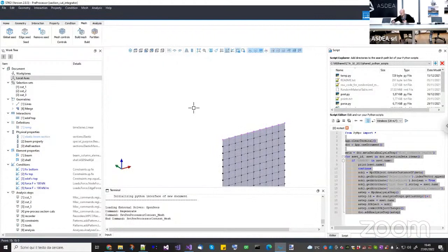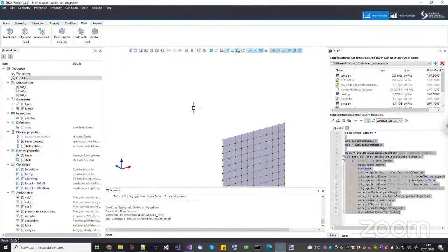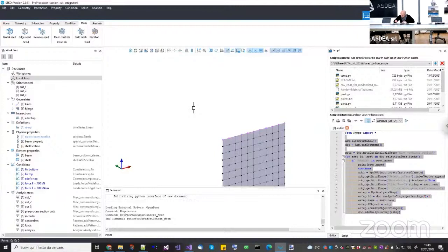Well, I can do it with this one. It works like the section cut with force sum in Midas Gen. So for example, if Valentina chooses to create a cut here, I will take all the nodes there. I will take all the elements on one of the two sides. Then the script will allow you to give a local axis orientation, like this one will be the Y, this one will be the Z, and this one will be the X. And then I will take all the element forces at these nodes coming from the elements at the bottom. So for example, here you will have a force like this, force like this, and then you will also have horizontal forces.